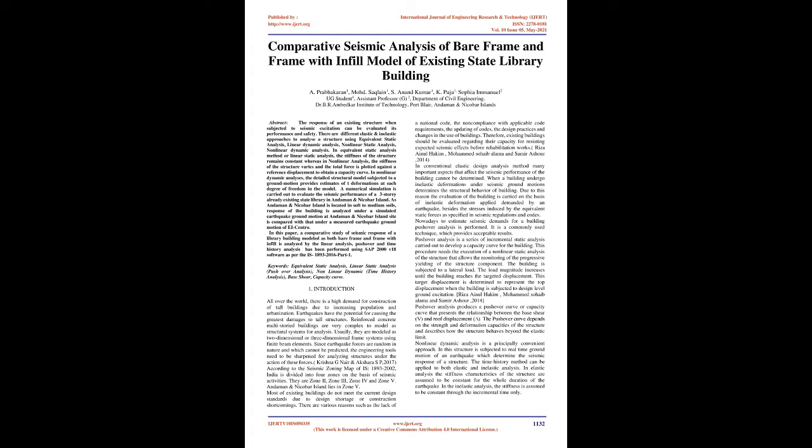In nonlinear dynamic analysis, the detailed structural model subjected to a ground motion provides estimates of deformations at each degree of freedom in the model. A numerical simulation is carried out to evaluate the seismic performance of an existing 3-story state library in Andaman and Nicobar Islands. As the islands are located in soft to medium soils, the response of the building under a simulated earthquake ground motion at the site is compared with that under a measured earthquake ground motion of El Centro.